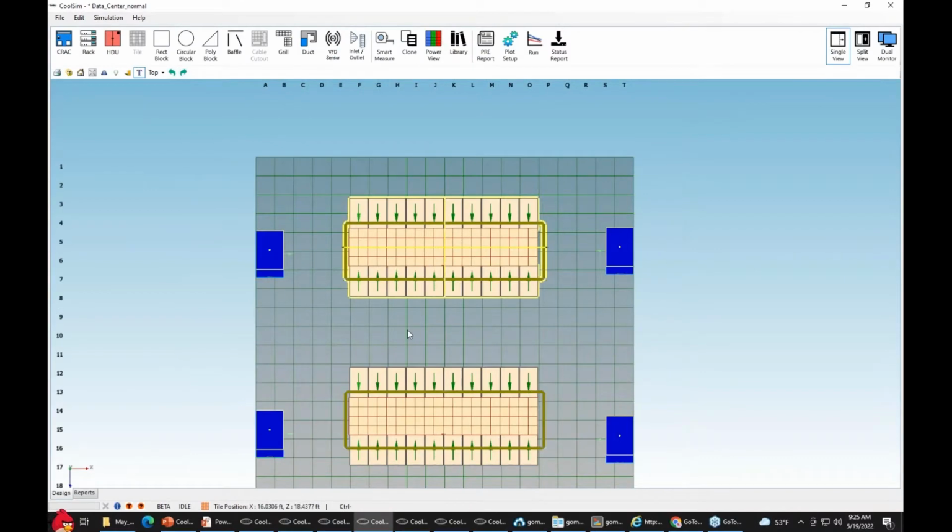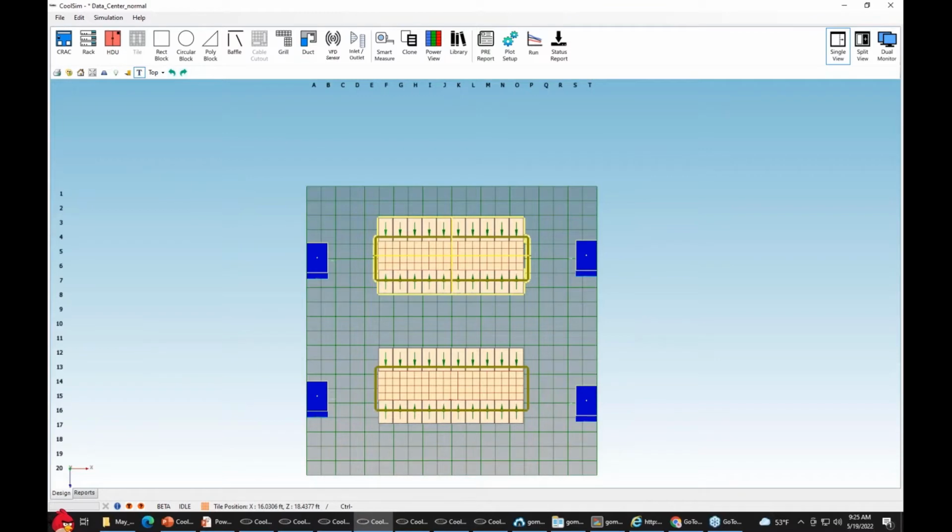So this grouping is very handy for multiple structures. You can even group everything in the entire room and export it, create a new room and import it back in. I use that sometimes when I'm having trouble with the model and I don't know why. I sometimes build a new room, export all the geometry, read it back into the new room, and try that. That's a method that we've used before for diagnostic.